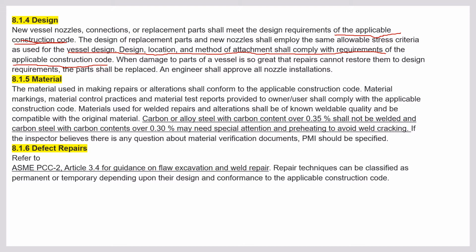The requirement is that the design of replacement parts shall not be below the original strength. Okay, that's what it is saying. That is how the design will be. Okay, and the engineer shall approve all nozzle installations. So the nozzle installation will only be approved by an engineer. Okay, not by the inspector, only the engineer.